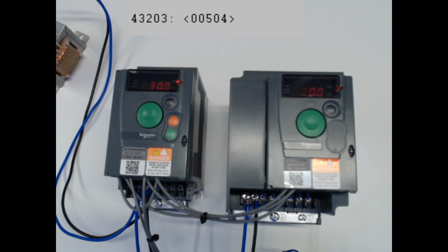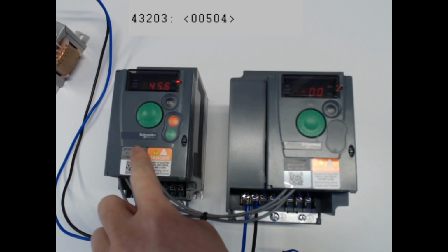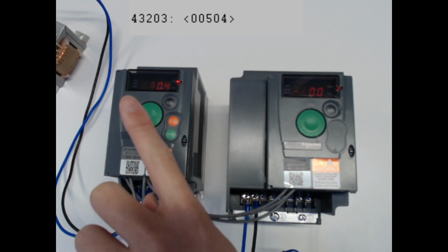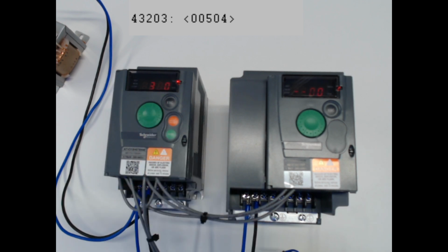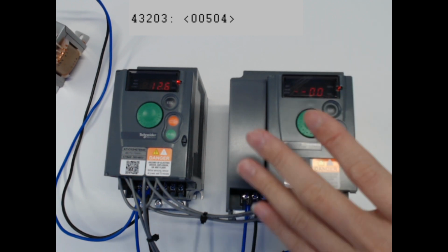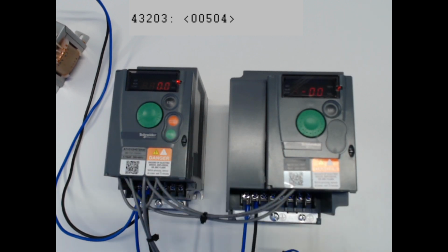Okay, so now we wait for a while. You can see that the aux pump will turn off and the main pump will shoot to 50. Okay, now you see it's at 50, but my pressure is still not changing. It's still above, so it is going to ramp down slowly. Okay, so now the aux pump is at dash dash 00. It is already destaged, and now after the delay, the main pump stops.